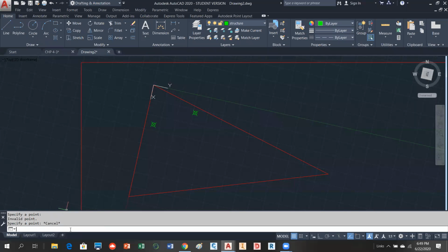We're going to now move the UCS, so the instrument is going to be here. We're going to backsight here. So we're going to go back to UCS object. You're going to select this object and notice how it's flipped it. Okay. So basically it's just flipped. That was where the occupied point was last time. Now it's here. So we're going to plot point 52. This was point 50. That's 51. Now we're going to do 52, which are the 3 points on that tank.